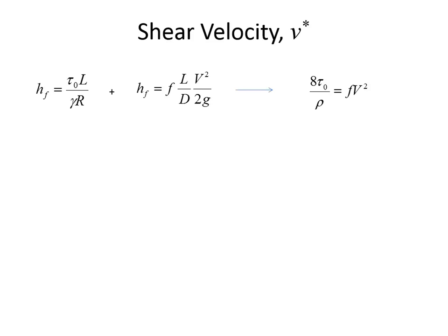So that's hydraulic radius. And so when you have a pipe, then you need to look at the shape of the pipe. The shape parameter goes into the hydraulic radius, and the length of the pipe between two sections. You can calculate the energy loss due to pipe friction if you know the shear stress. And you could also know the energy loss due to pipe friction by estimating the friction factor F. And so if you combine those two things together, then what that gives you is a relationship between the friction factor F and the shear stress, the boundary shear stress tau.